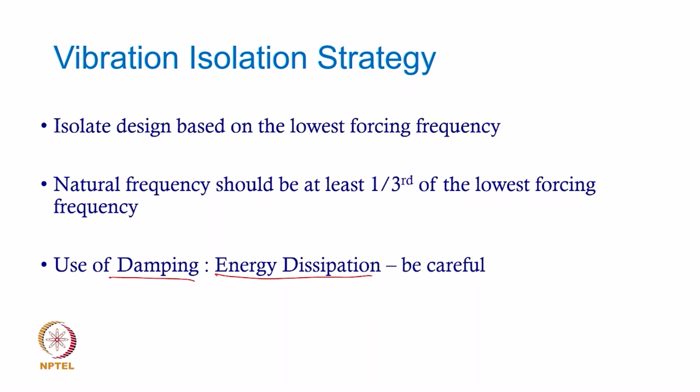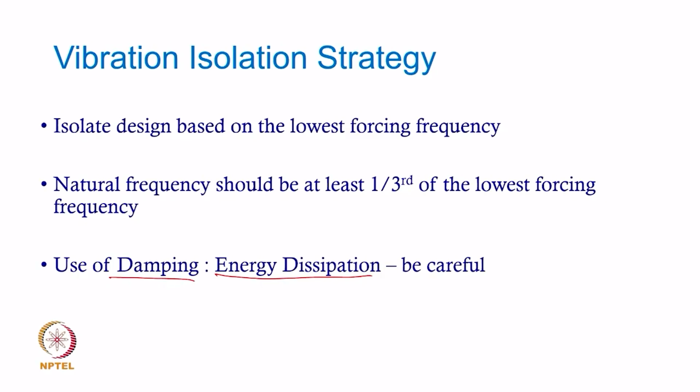at all. Okay. Of course, there are other situations where you need a good amount of passive damping to take care of instability issues, but those are generally not encountered in normal vibratory systems, except when you have very high speed machinery, then the issue of instability can arise, and then some amount of additional damping could be useful. But as long as you are clear about what your system is and how much damping it needs, you do not have to use excessive damping in the system.